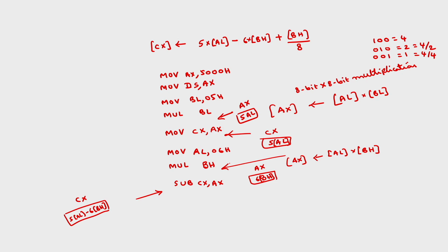So, if I take a 4 bit number, for example 1000 which is equal to 8, and shift to the right by 1 bit position, this will be 0100 which is 4, one more bit position 2, one more bit 1. Okay. So, after 3 shifts, this value became 1 which is equal to 8 by 8 which is equal to 1.